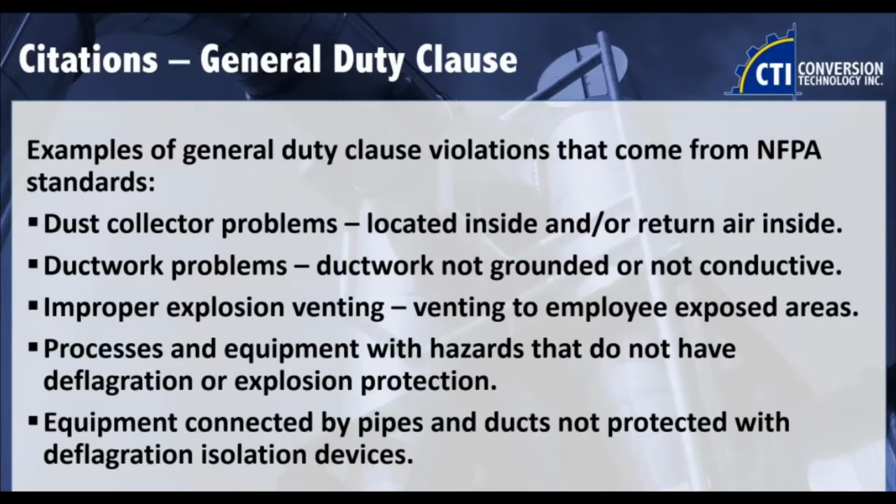I know that was really fast, but I get asked that probably the most out of anything is about returning air. Otherwise, there's ductwork problems, explosion venting that might not be sized properly, or if you have an explosion relief panel on a dust collector and that relief panel, if it blows, it goes right into the front door of the break room, well, they can say that's a potential hazard, and that's kind of where they'll get you. But specifically, the NEP uses the general duty clause to issue citations for primarily going to be the deflagration or explosion or fire hazards within dust collection systems, other containers like mixers, bins, silos, things like that.